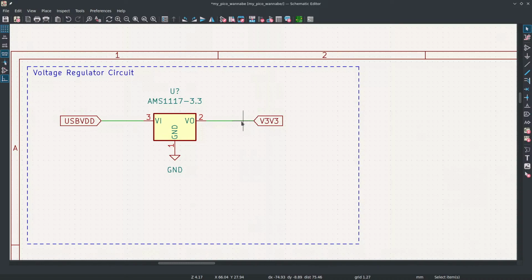Linear voltage regulators usually give the cleanest power out of everything, because they're not doing what switching regulators do and making it noisy. You'll see in a lot of audiophile equipment, they'll advertise that it's a linear regulator, and they'll have a massive heat sink on it to dissipate the power, because it does create less noise in the circuit. So they're a pretty safe choice when you're able to fit that into your power budget.